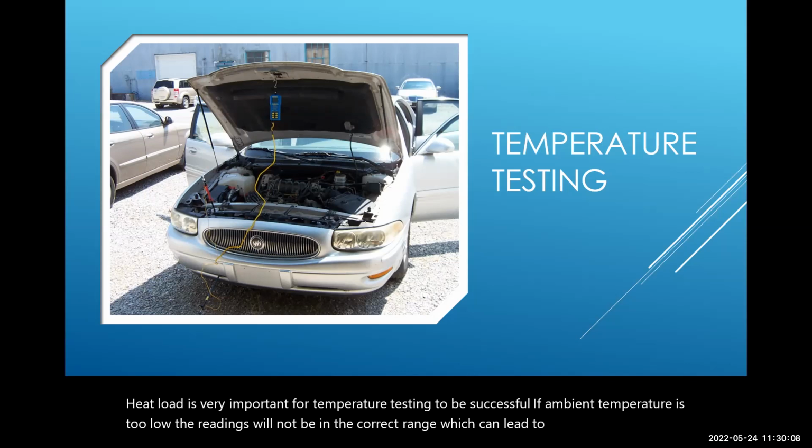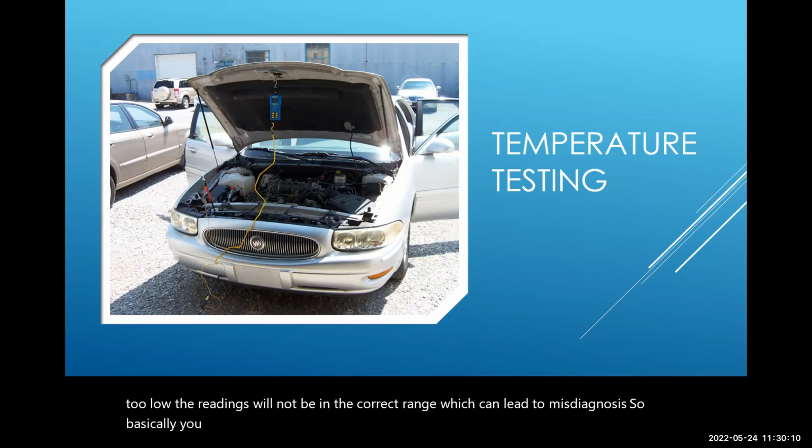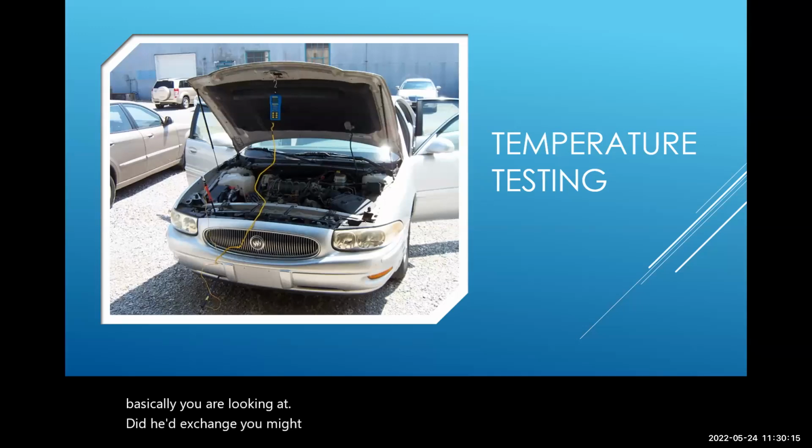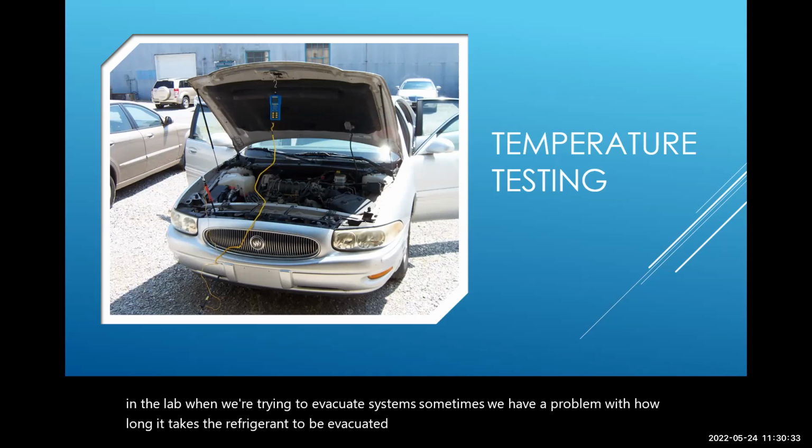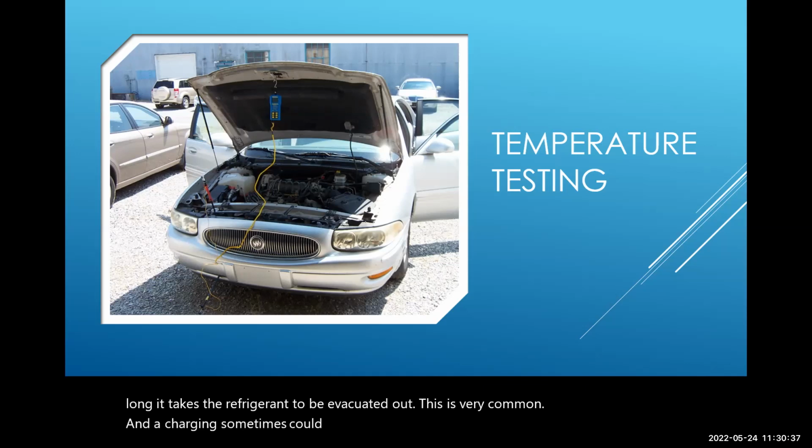So basically, you are looking at the heat exchange, you might put it that way. And if it's outside temperatures like we've seen in the lab, when we're trying to evacuate systems, sometimes we have a problem with how long it takes the refrigerant to be evacuated out. This is very common. And charging sometimes could be a problem too when you get into the colder climates.